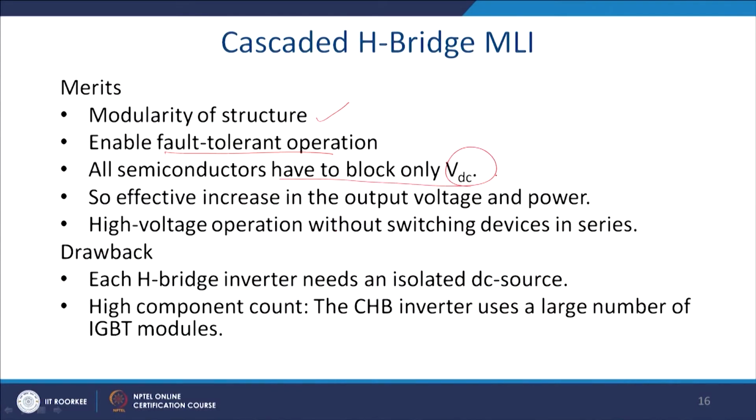All the semiconductors only block the voltage level of VDC. So, the output voltage and power level can be enhanced, and if you put in more bricks you can increase the voltage rating.